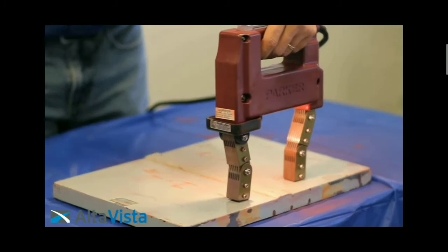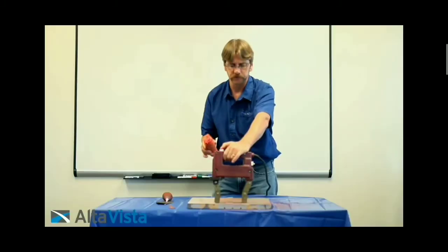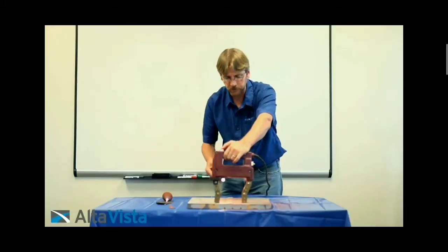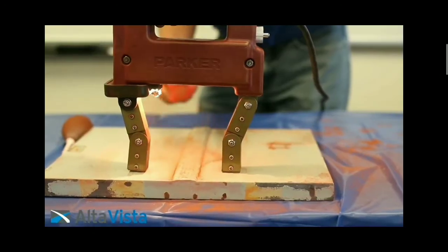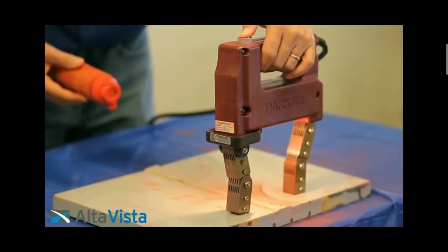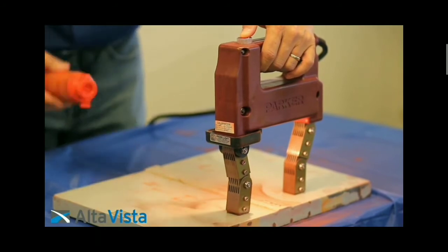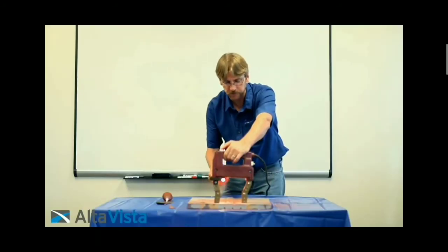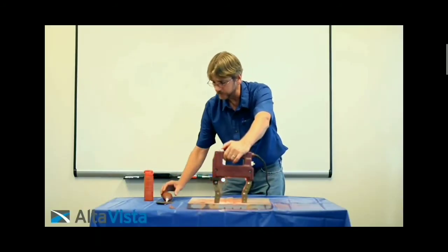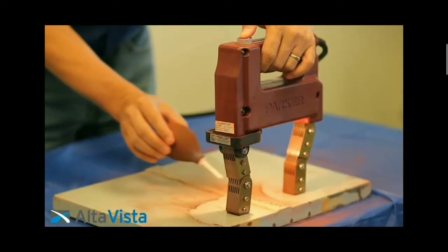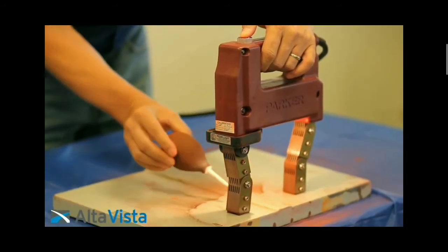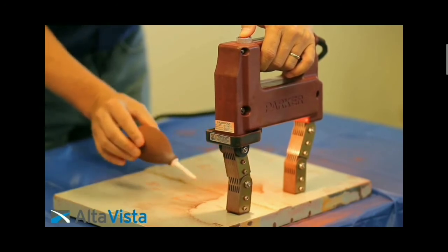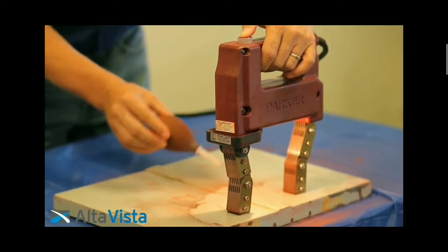One of the things that we teach our technicians is the proper technique for applying the particles. As you apply the particles, you want to just float them on. You don't want to dump them on with a can such as that. You just want to lightly float the particles on. And the same thing with a puffer. When you blow the particles away, you want to be a little tender and sensitive and make sure that you have the right technique.